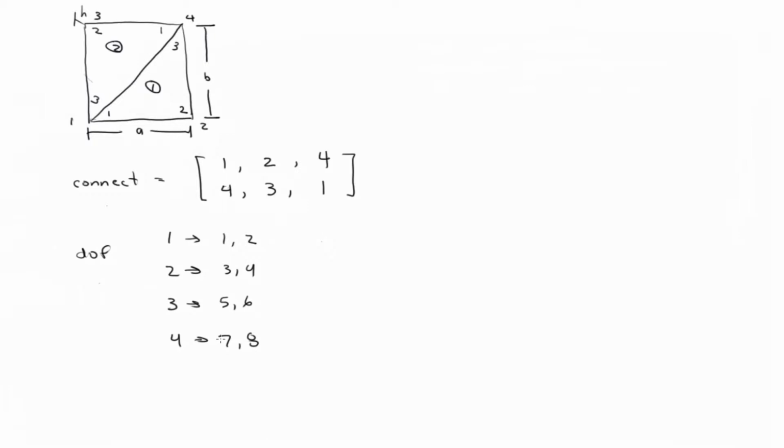In general, there's no optimal way to do it. But there are, based on graph theory and other things, ways to come up with better node numbering schemes. In other words, I could switch around the local node numbers so that my connectivity array is different, and that would give me a better sparsity structure in the matrix. And yes, that is important, and it can speed up the convergence of iterative solvers. But there's also a trade-off, because it takes some time to do that. Of course, it's usually something you just do once, right up front, but there is some time associated with it.